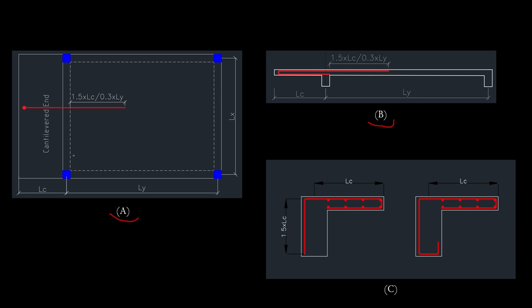To detail a cantilever slab, the main reinforcement in a cantilever slab is the top reinforcement, which you also denote as the T1 reinforcement. And the reason for this is that a cantilever slab moment diagram is always like this. This is how the moment diagram of a cantilever slab used to go. Don't mind my drawing. So this is the moment, and that moment is at the top. That is, the main reinforcement you need to provide for the cantilever slab is to provide that reinforcement at the